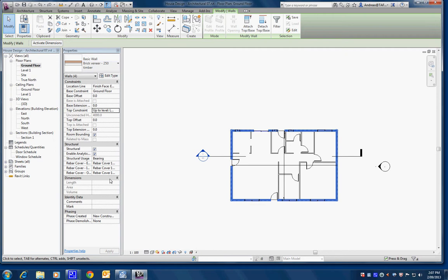So now I can go into the base extension, which is this one here, and change it to -20, so you can lower the bottom part of it. And we've got to go to the top extension, okay, this one here, and make that -110. Alright, so that's just the number I figured out for you. If I go apply, that'll fix that up. Okay, and so, yep, where is that? Gotcha.